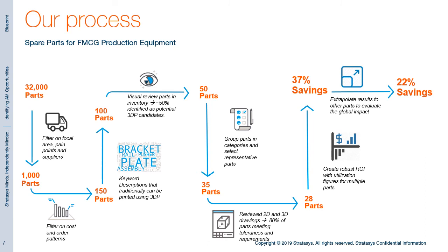At the end, it was estimated that 3D printing can be around 22% saving on the 1,000 machine parts that were ordered from the selected supplier. This is taking into account the saving for our representative part and our confidence level for each category. This saving only occurs once we are at full production, as it takes some time for the current stock holding to be depleted and 3D printing to fully replace the current methodology.